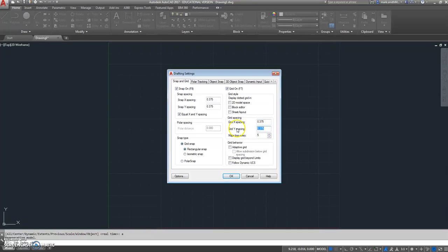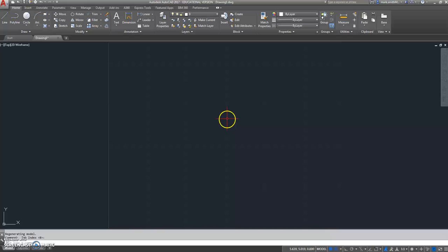We're going to temporarily suspend our rule, and we're going to set it to that. And you can see it's changed. You can't see the snap operating until you're inside of a draw command. Now you can see it snapping. Okay, so if I go back and I look at my basic setup procedure, my LT scale should be 0.5 times 1, which is 0.5.